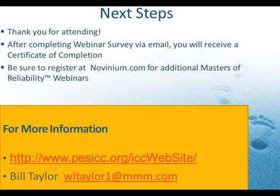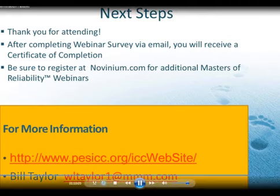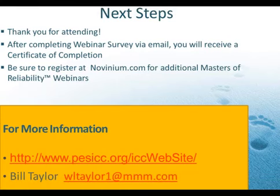If that bleeder wire is not there and it's totally insulated from ground, that leakage current will find its way to ground through whatever material is in the way, and it'll eat up that material and eventually cause you to have problems and potential failures with your system. If you're talking dead front, which we'll be talking about later in one of the webinars, it's very important that you have that dead front, either elbow or T-body, grounded in order to ensure that it's at ground potential.